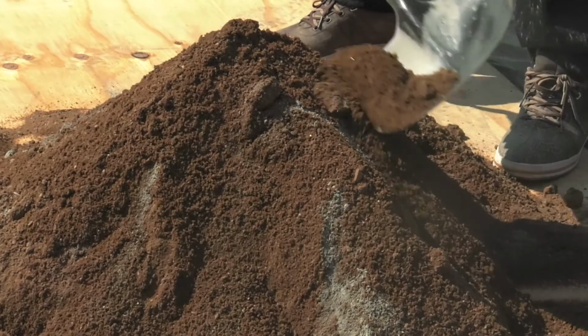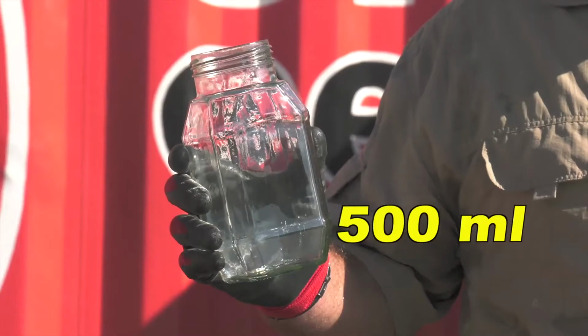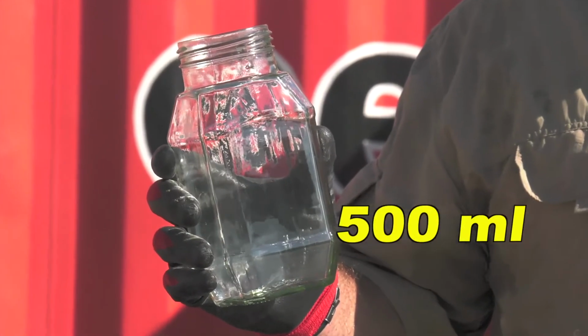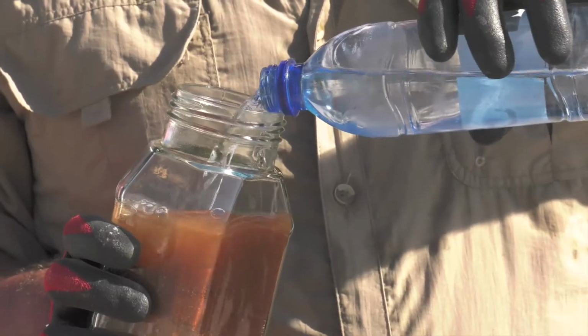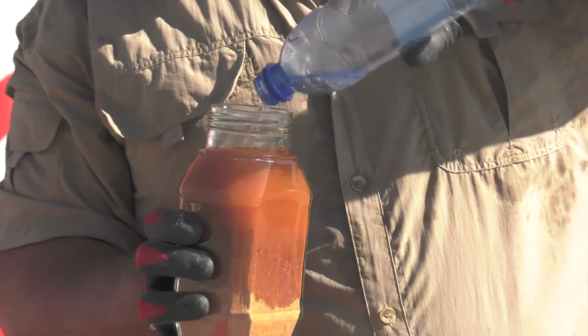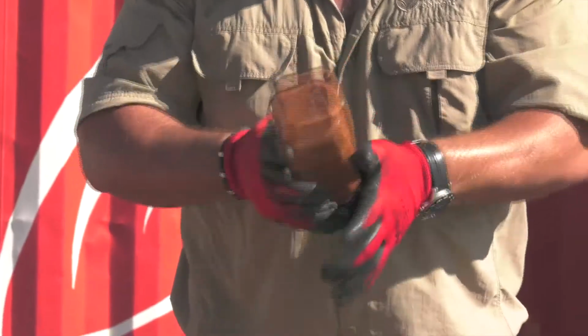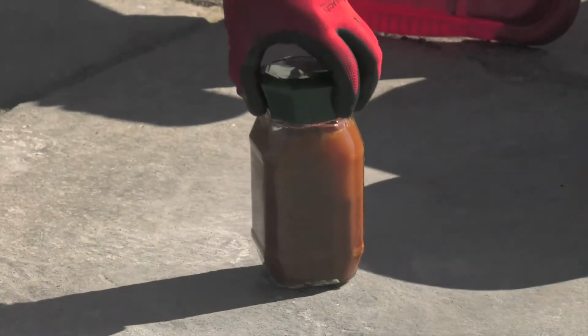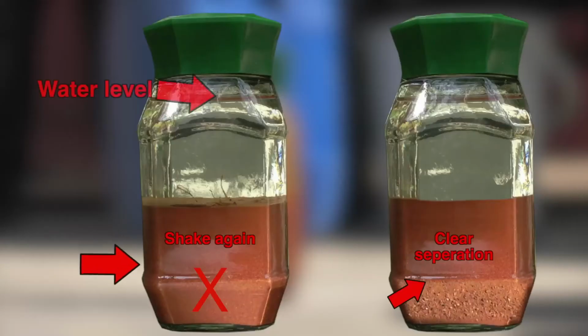In order to be sure whether the sand is suitable to use, you can do the following test. Take a small, clear 500 ml bottle and fill it halfway with the sand you want to use. Add clean water to the bottle until it's almost full. Close the lid and shake it well. Let the bottle stand for about an hour for it to settle down until the water at the top is clear. If you do not see a clear separation between the layers of the sand, shake the bottle again and let it stand for another hour.